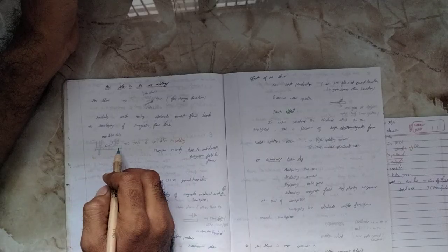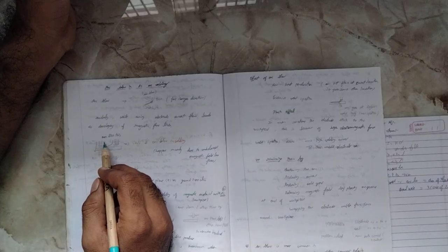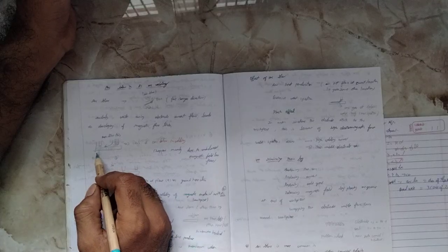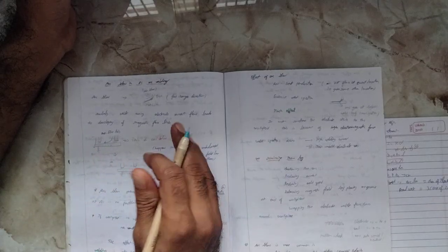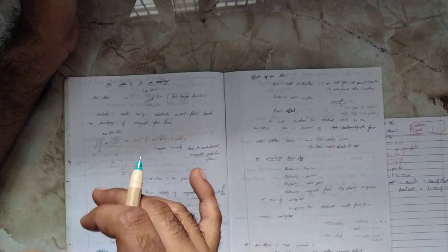Okay, so you can see this side is connected to positive and the entire workpiece is connected to negative. The transfer of electrons here and here should occur very quickly. But whenever the electrode is passing here, the transfer of electrons from here to here should occur. So this is called arc blow. With this kind of arc blow, the arc won't be that stable.